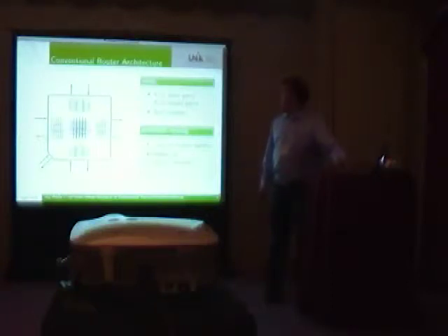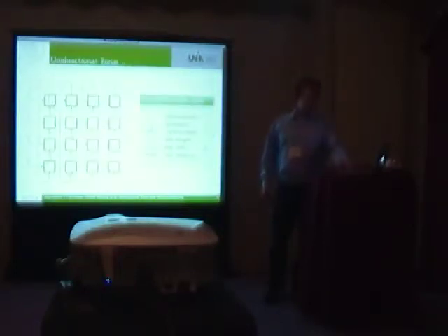Then to improve the throughput and to avoid deadlocks, you use virtual channels. So for every port you need more than one buffer. And you need a lot of logic to control all of this. Typically this logic is pipelined because there are so many things to do for forwarding a message through the router. Now, what are we doing different?